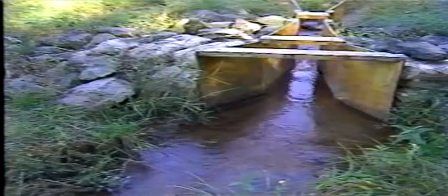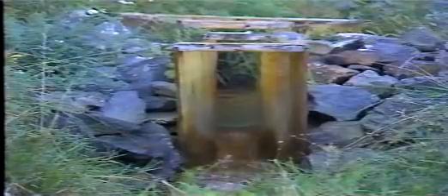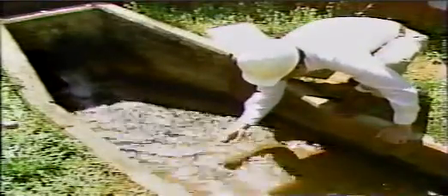Weirs and flumes are used to measure the flow of water. Check to see that the staff gauges are legible and have not been moved or damaged, that water is not bypassing the device, and that debris is not blocking the flow of water. If you find any of these problems, correct them. A buildup of silt in a weir box may mean that piping is occurring. Also, note changes in the amount of flow and look for cloudy water. Report cloudy water to an engineer or other appropriate person.